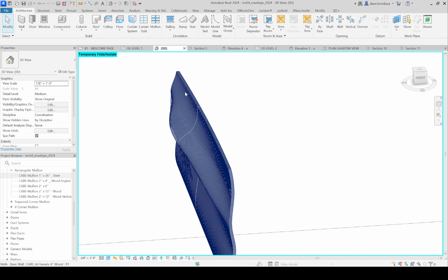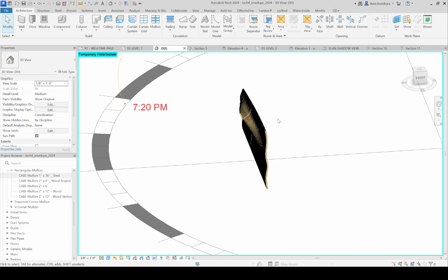To do this, I have to do three things. Anything in Revit that is curvilinear in shape, or has funky slants or tessellation on it that's not a roof or a floor, you need to first build a mass that represents the form you want to attach something to. Then you can apply walls, roofs, and ceilings to that mass, right?